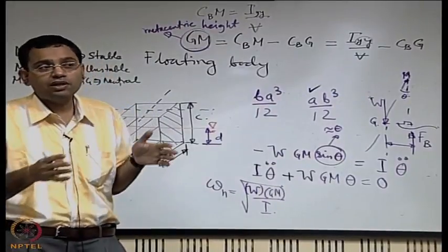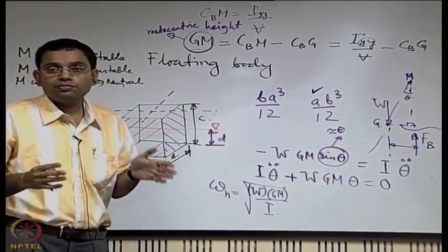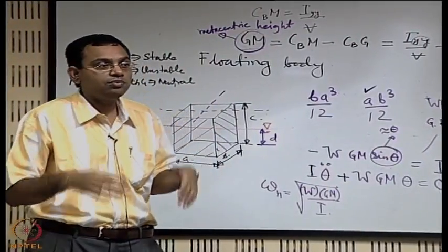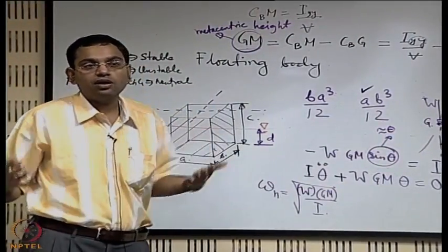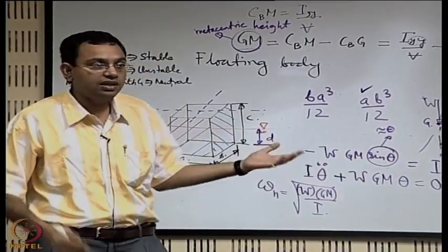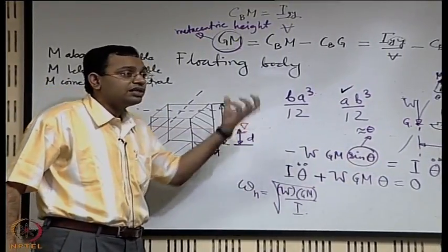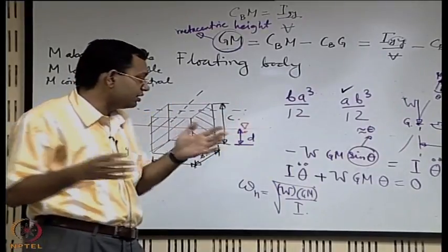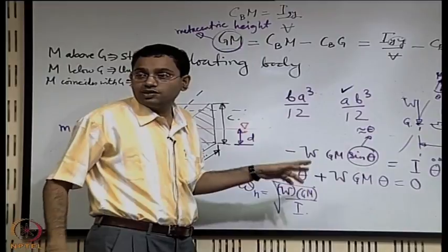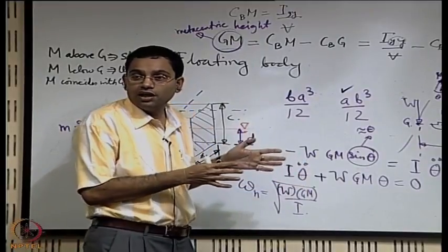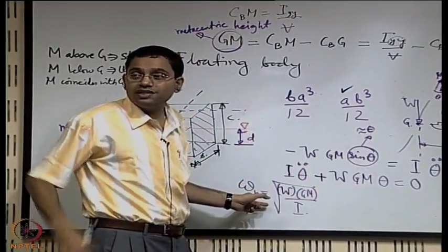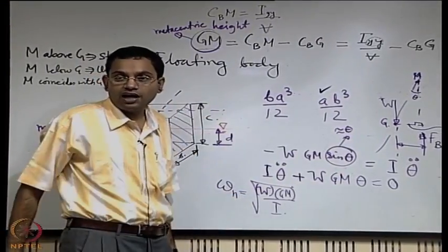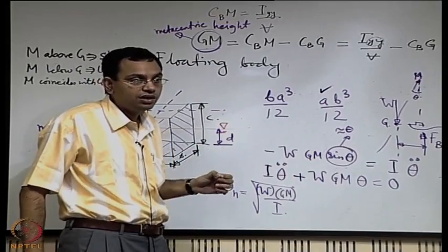At the same time, if it is used for a critical purpose like warfare, the stability of the ship is more important than the comfort of the crew, and there it is the stability that should be the driving factor for design. So when a ship is designed, you have two conflicting things, one is comfort, another is stability. The comfort factor comes from this high frequency of oscillation, and the stability comes from the metacentric height, or the location of the metacenter relative to the center of gravity.